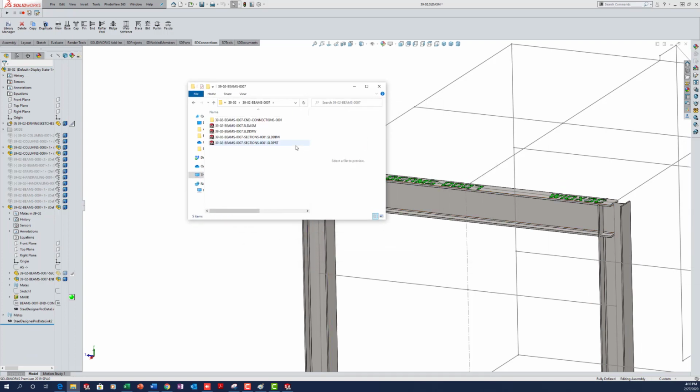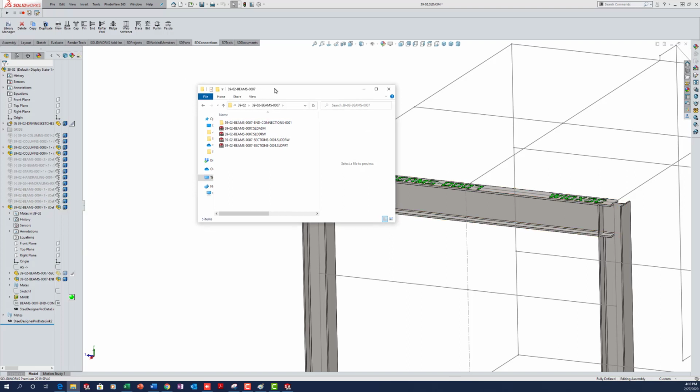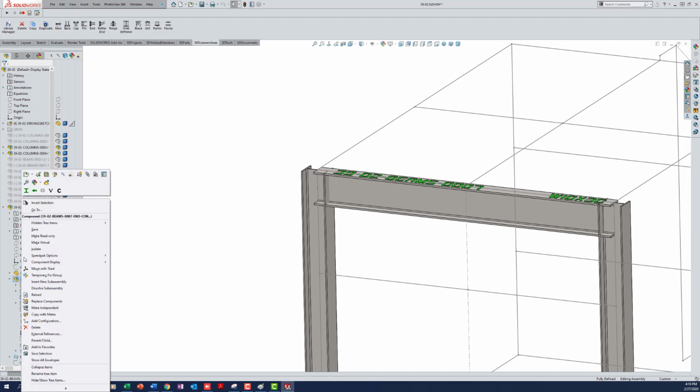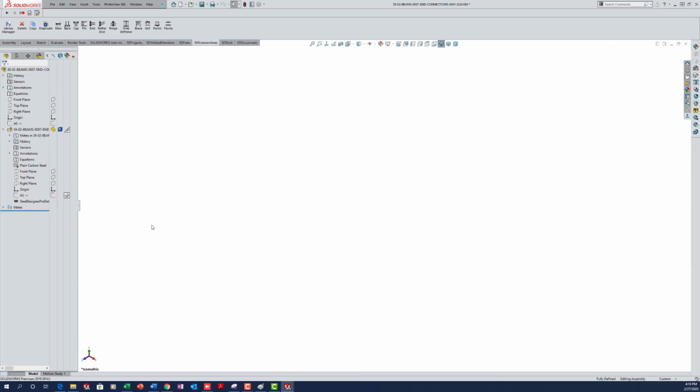Under Beam 7, now there's a connection folder. All the information for this connection resides in that folder. This connection is mated to a 3D sketch point and mated to the section inside the welded member. Its attachment sketch has become aligned with the welded member attachment sketch. So now we'll open this connection and fill out the rest of the information.